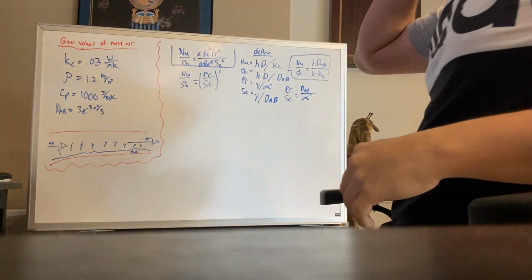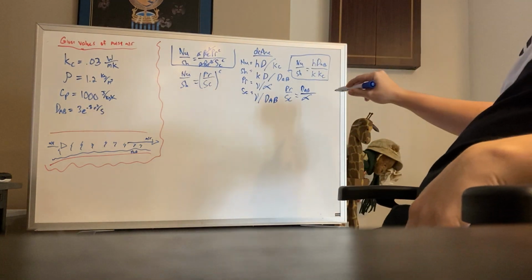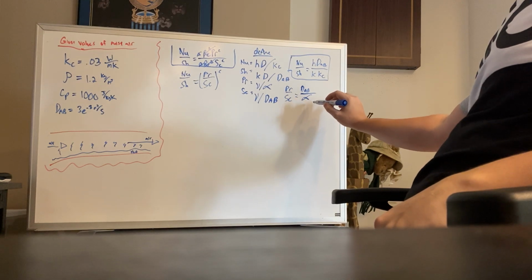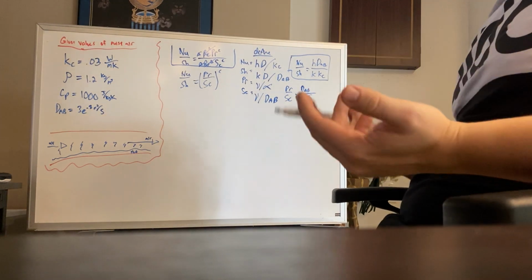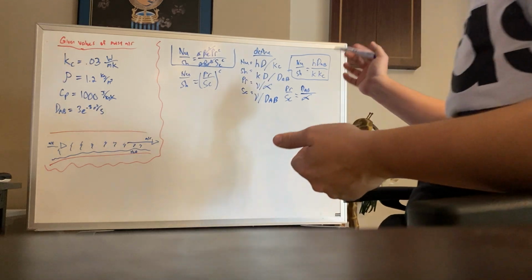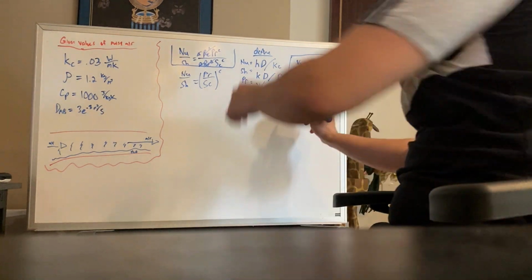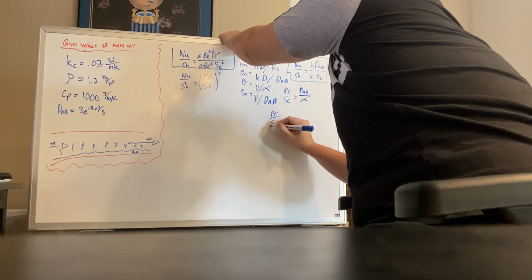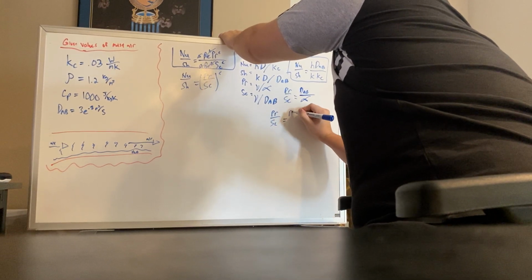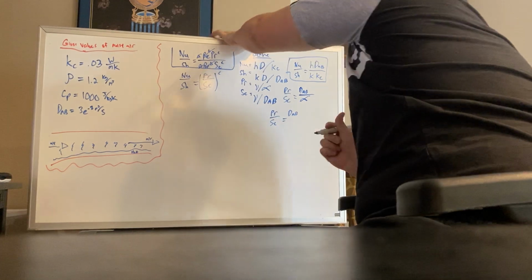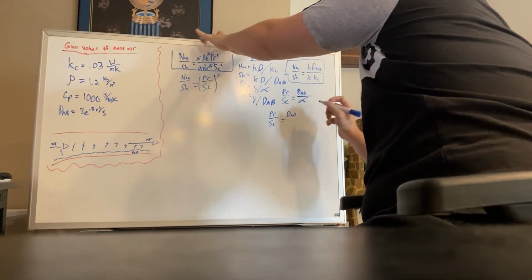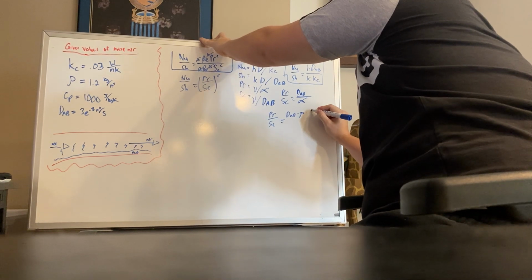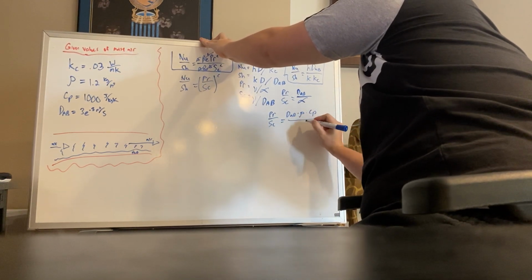And so that's pretty much what we're left with at the moment. But the thing is that we can actually go through and expand this and get rid of this thermal conductivity coefficient as well. And so what we can do is change this into the diffusivity constant. So I'll just rewrite it right underneath: the Prandtl over Schmidt equal to the diffusivity constant between components A and B, and then this will be multiplied by the density and the heat capacity, and then this will also be all divided over